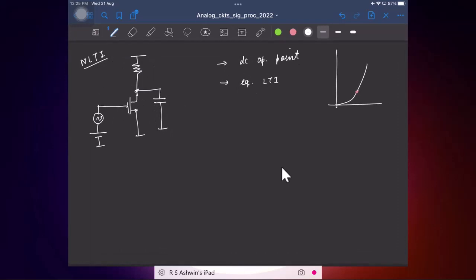Okay. So the point I want to convey is, if you have just an LTI system, and you are interested in finding the frequency response, you could directly run a .AC analysis by skipping the DC analysis, right? You don't need to compute any operating point as such, because the circuit is linear.